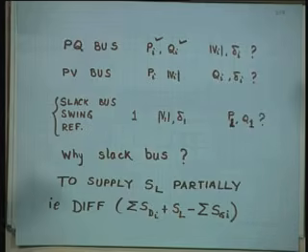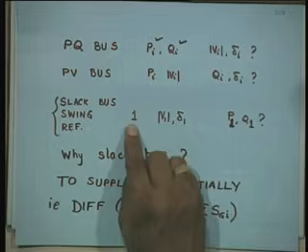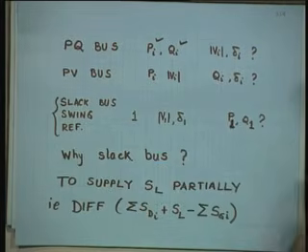So, these are the different names given, and if it is asked in an interview you should not worry what is a generator bus. Generator bus normally means PV bus, a load bus normally means PQ bus, and similarly I have written 3 names here: slack, swing, reference. There is a meaning to each name. Let us start with the reference bus. Mind it, there is only one such bus, that is why I have written this 1 here.